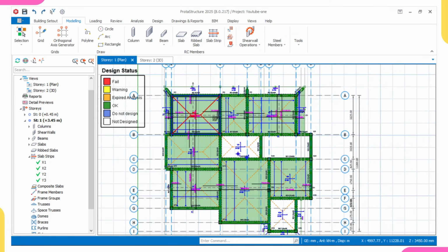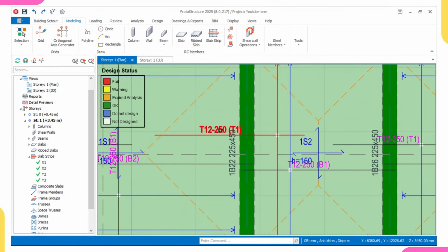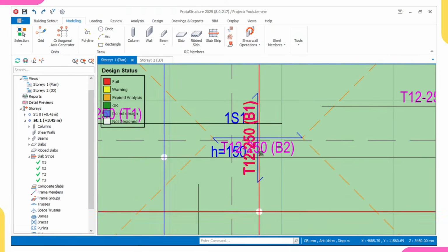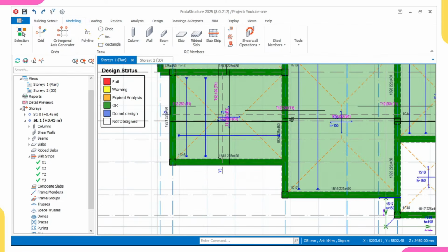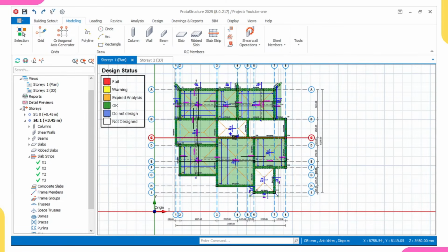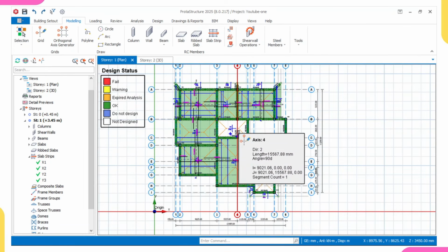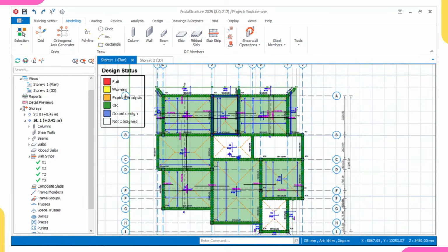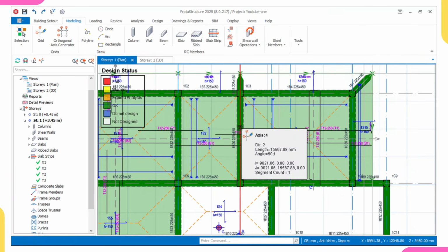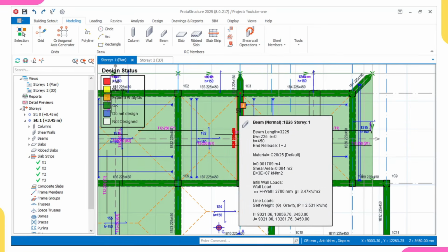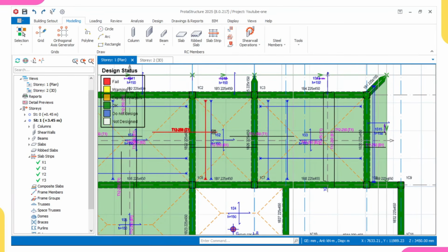In your own, you do it accurately. But me, if you look at everything here, I'm having Y12 at 250 spacing everywhere. In my own detailing, what I use is Y12 at 200 spacing. The reason is still what I told you concerning beams. I'll use Y12 at 200 spacing because in most African countries, even where I'm located, which is Nigeria, most of our companies tamper with quality.